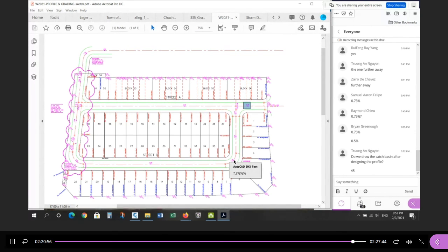Okay, so now we need a few more key points. Again, I'm trying to avoid using vertical curves, so I don't want to have a grade change of more than 1%. I'm going to approximate vertical curves without breaking the rule. If there's a grade change of more than 1%, you need a vertical curve, so I'm going to do my best to avoid that.